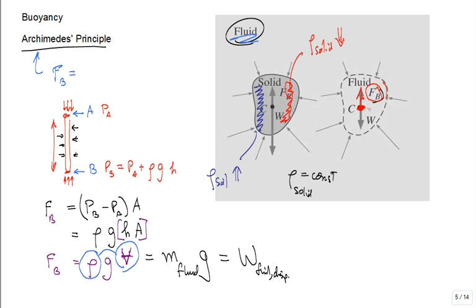What about where should I apply that buoyancy force? Should it always be at the centroid of the volume? Yeah, it should be. All right, now think about the weight. Did the weight depend on the density of the solid? Okay, let me go back up here to the buoyancy force. Did that depend on the density of the solid? No, you're getting better. You're getting really good.